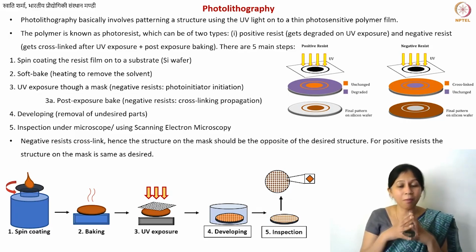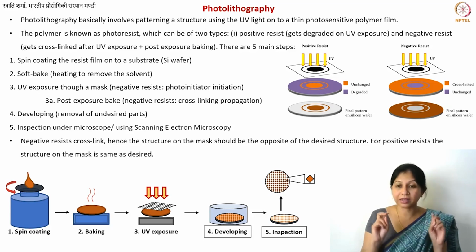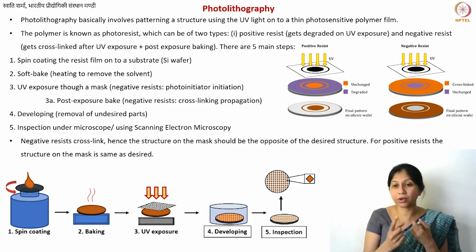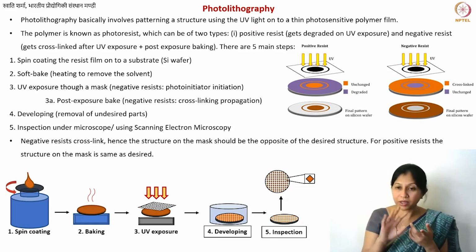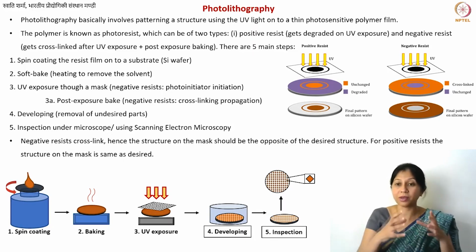These are the most common parameters that are used for glassy carbon based microfabrication. Number one, you use silicon wafers with or without oxide films depending upon your application. Number two, you use this photoresist, a phenol formaldehyde resin, which is a negative resist, SU8, and it is available in different viscosities. You use 900 degrees centigrade pyrolysis temperature, a ramp rate of less than 5 degrees per minute, and an inert environment for pyrolysis, and now you get your carbon structures.